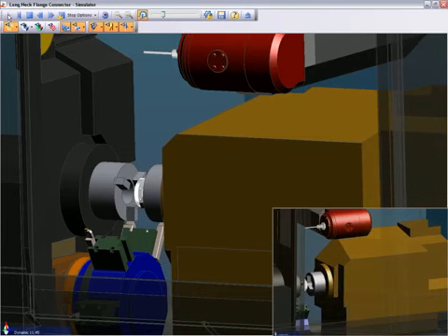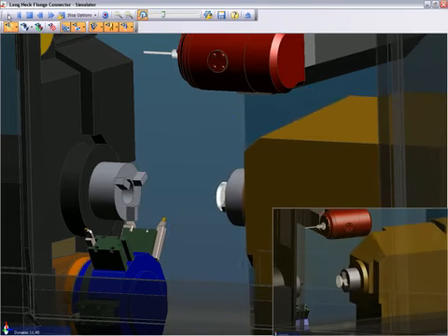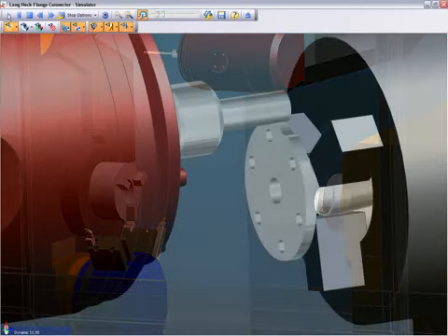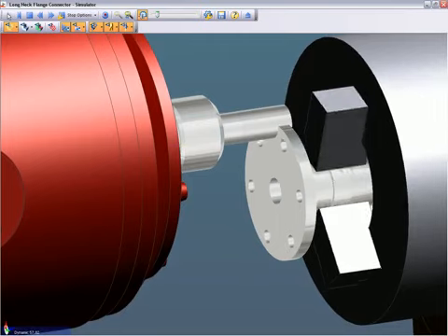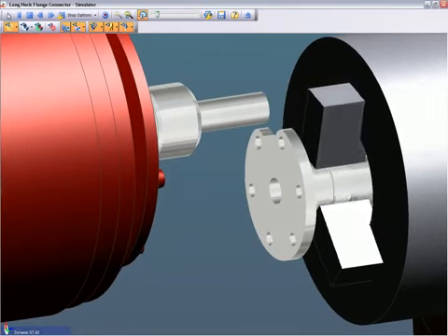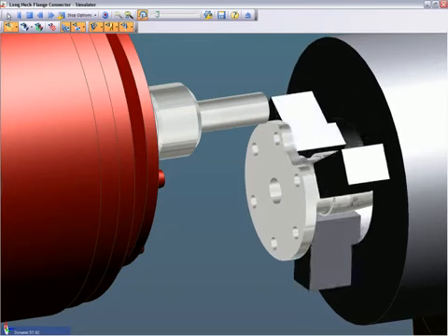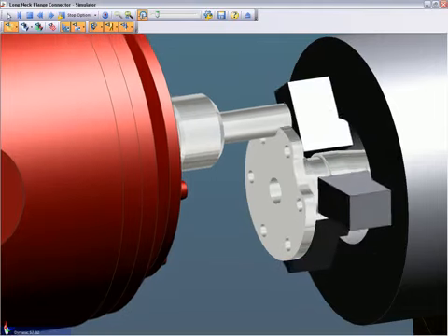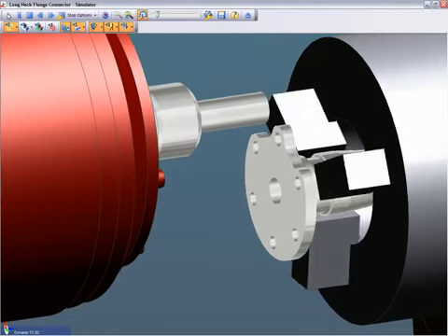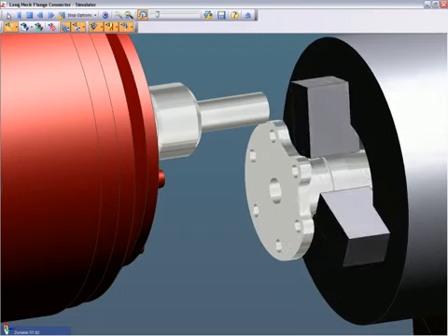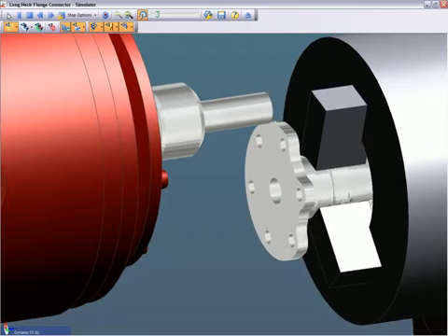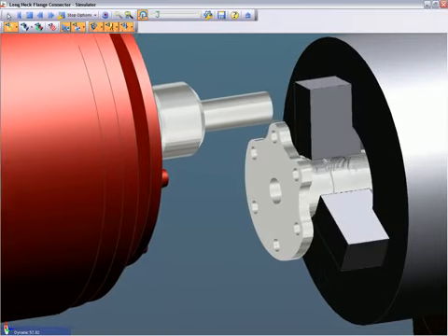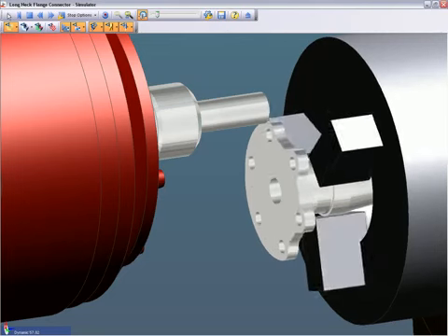So let's review what you've seen in the past few minutes. The solid model was loaded directly into Edgecam without the need for third-party translators. The strategies use the information from the manufacturing features to select appropriate tools and cycles, including the correct speeds and feeds. The decision of which tools and how they were applied is driven by your company's best practice. Simulation confirms the correct method of machining, reducing the prove-out time. The end result is posting of good, clean, edit-free G-code straight to the machine, and at the end of the day, this is the true product of a CAM system.